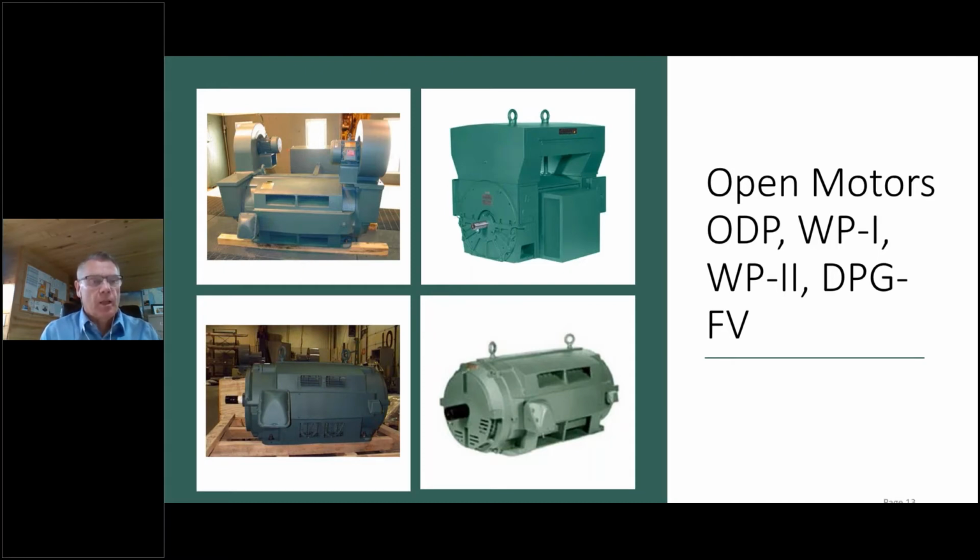The top left-hand picture shows some assisted fans. We call these piggyback blowers. You'll see these separately ventilated, fan assist, or blower cooled motors in applications where the motor is either running in a very hot environment or, most predominantly, when you're on a VFD and using a much slower speed range.